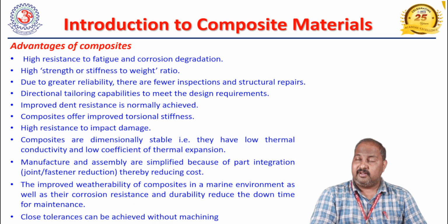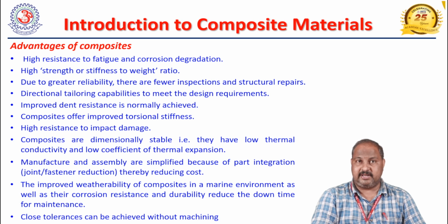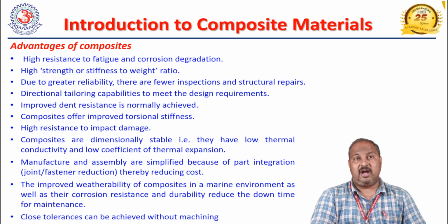during its service. Coming to the next, the advantages of composites. Major advantages are the high resistance to fatigue and corrosion degradation, and high strength to weight ratio, or stiffness to weight ratio. That is what I said, high specific strength or high specific modulus. These are some of the important advantages of composites compared to the monolithic alloys. That's why most engineering applications nowadays, especially advanced engineering applications, are aiming towards replacing the monolithic conventional alloys with